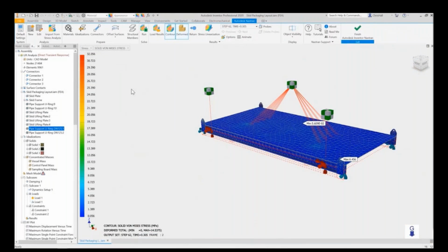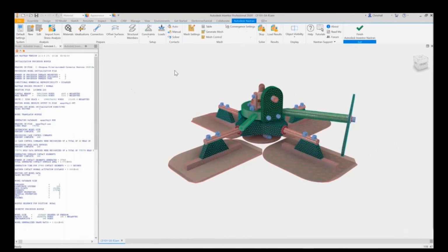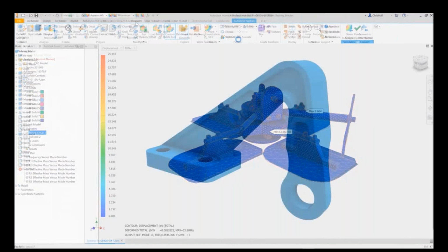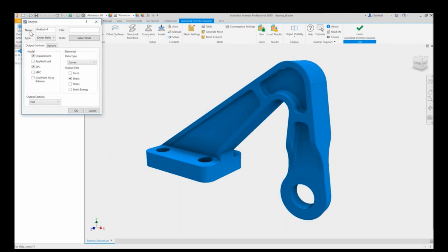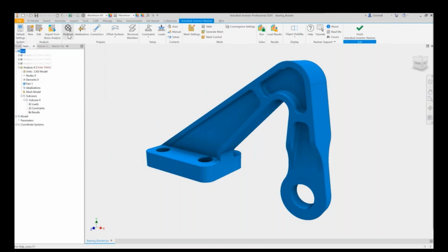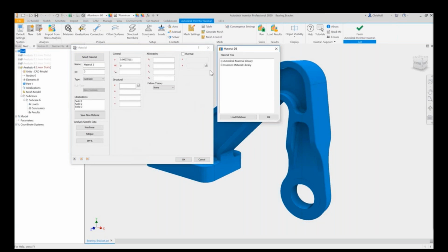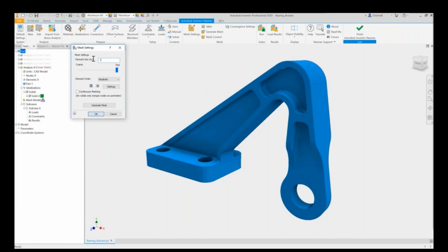Autodesk Inventor Nastran is an in-canvas Inventor toolset for performing finite element analysis using the Autodesk Inventor Nastran solver. In this video, we will introduce you to some of the powerful capabilities of Inventor Nastran. To access Inventor Nastran, click the Environments tab and select the Autodesk Inventor Nastran button. In-canvas simulation tools provide a wide range of simulation types, including statics, dynamics, nonlinear, composites, and heat transfer.